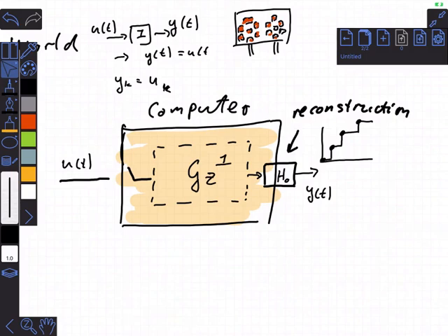A digital box can completely reproduce an analog signal flow as long as we allow for some latency, as long as we allow it time to do its thing, right? But the reconstructed output will always be delayed if we're actually working in real time. You can refer back to our filter discussion to understand why. The more of the signal I'm using to do the reconstruction, the longer I have to wait to actually receive those samples, which means I cannot report those answers faster than at least that window of signal that I'm using. And because of that, there's always a delay.